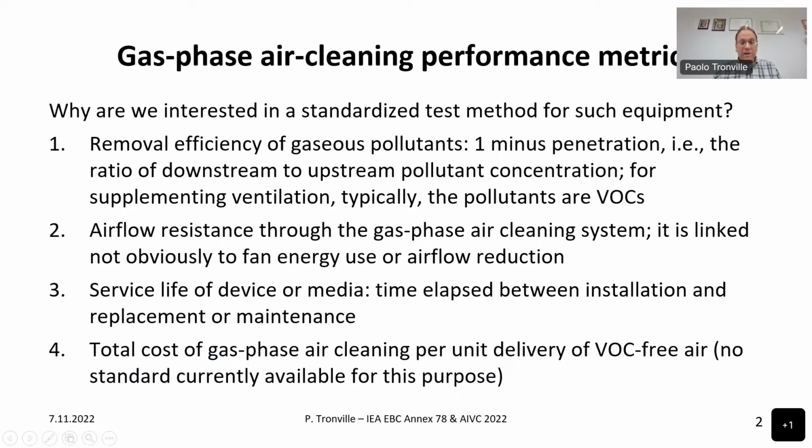The first one is the removal efficiency of gaseous pollutants. The efficiency for gas phase cleaners is actually expressed as breakthrough, that is to say the penetration that is passing through the device. So the efficiency is one minus the penetration. And the kind of pollutant, in case we are interested in supplementing ventilation, is typically a volatile organic compound.